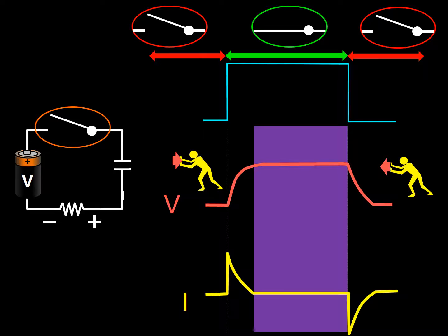When the circuit is open, that is, when the flow of current stops, the capacitor will discharge. The current at this time will be in the opposite direction to that which was initially flowing, since it is the electrons stored in the negative plate that flow against the direction of the original current that charged the capacitor.